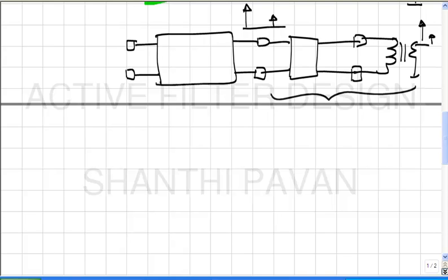But that won't do for distortion. If you test using this kind of setup, then the attenuation of the third harmonic will be different from the attenuation of the fundamental, right? Which means that you must account for that attenuation when you quote the distortion, right?